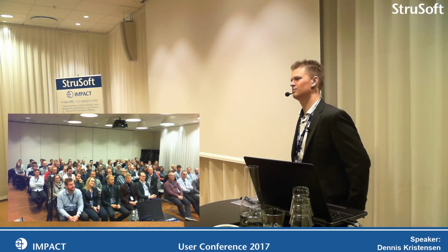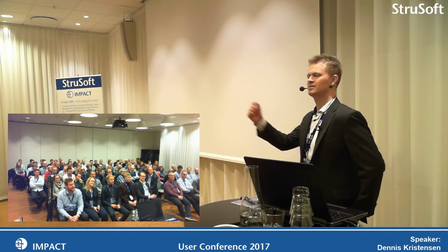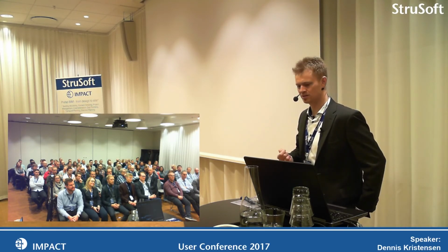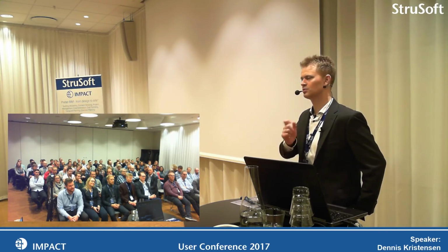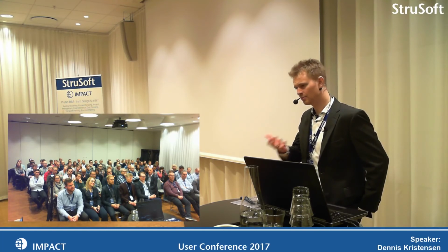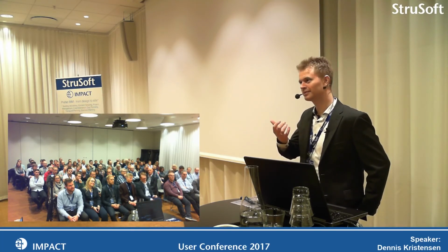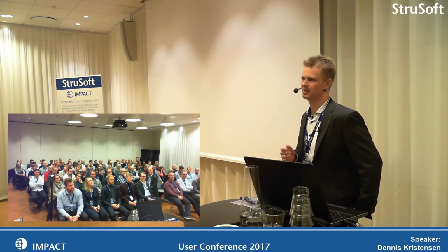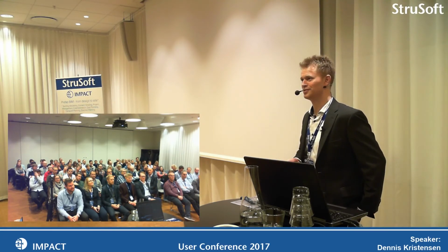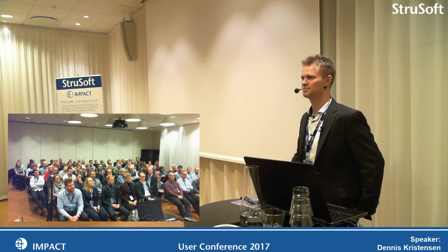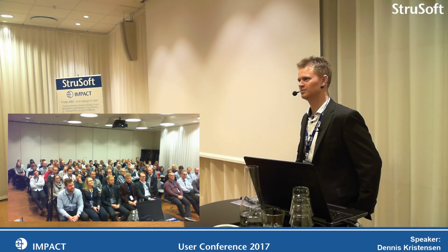We believed in it so much, but we were just ahead, so we scaled it down and moved our BIM focus to the Tekla and Revit connection. So right now you can solve it with a workaround: open it in Revit and send it to FEM-design. This is the only way that really works now. Some models in IFC work for some reason, some do not. The schema in IFC must be really exact for FEM-design to understand it.